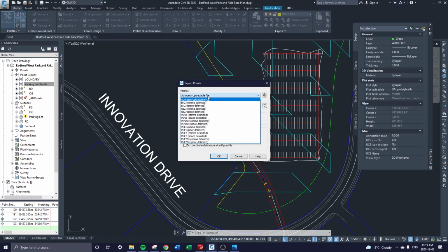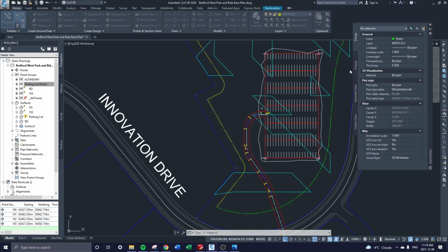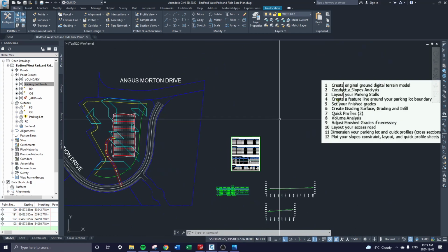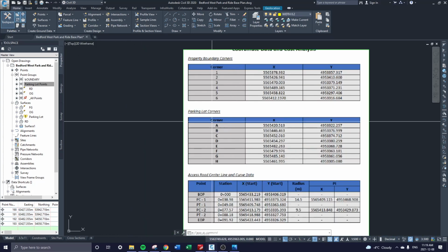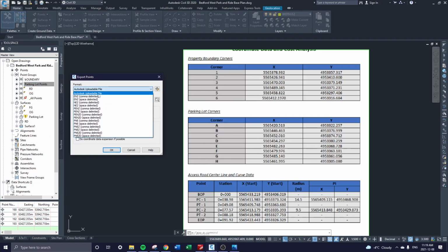Format. How do we want this to look? I'm just going to escape out of here so we can see how Paul's format is. So we want the point description, we want the easting and the northing. Okay, export points. So P, I think, let's see. Oh, okay, our description is actually going to be last. So we want northing, easting, which one's, yeah, so he wants it easting, northing, but whatever. As long as you label it, I'm sure it'll be okay.